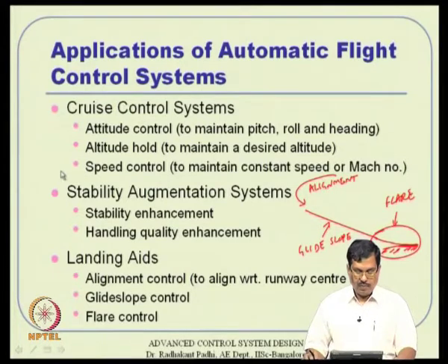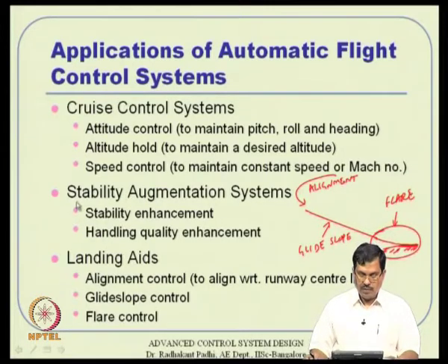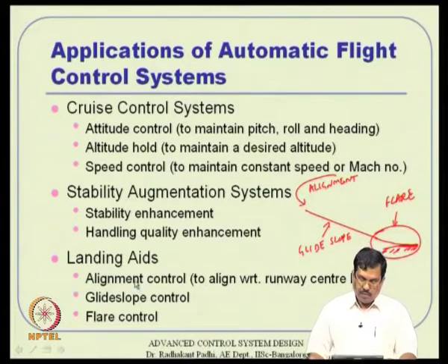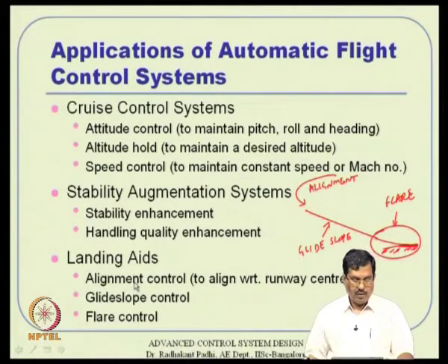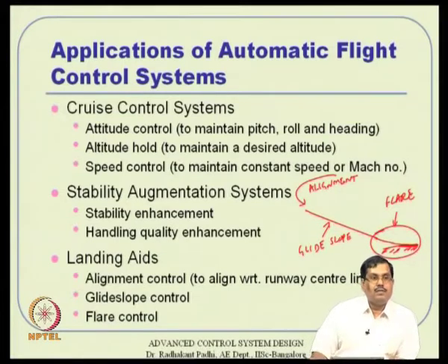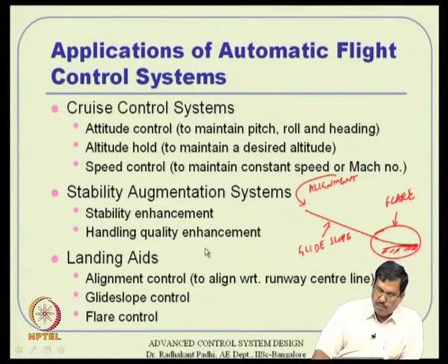Other than the fact that maybe a test pilot will know that, a regular pilot may not even know that. Okay. So, that is going inside the flight computer in a built-in manner, and landing aids are anyway there, and takeoff aids are also part of the deal. And there are secondary level flight control applications which we are not talking about here, like path design, guidance design essentially: where the aircraft will go, what direction it will go, what time it will reach and things like that. So, that is the guidance level, which is an outer loop control sort of thing.